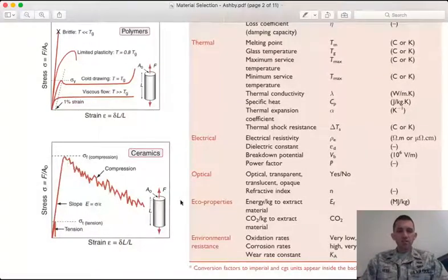And so a stress strain curve for a ceramic material might look something like this, where you have sudden failure, and in this case, I guess this is a compression test, you have successive failures as you have cracking propagating through the material. So in a compression test, you don't have one rupture. You have a series of them because you're compressing it rather than putting it under tension.